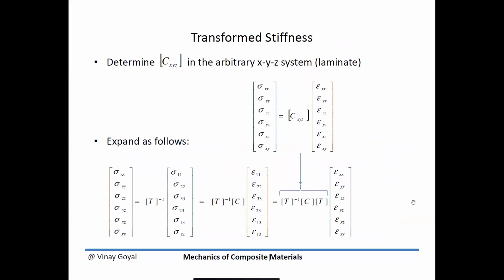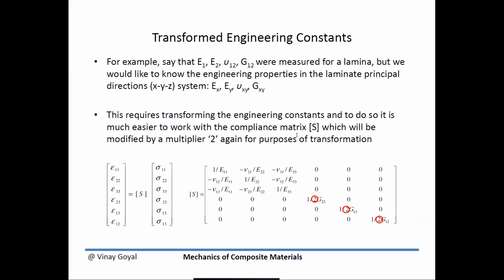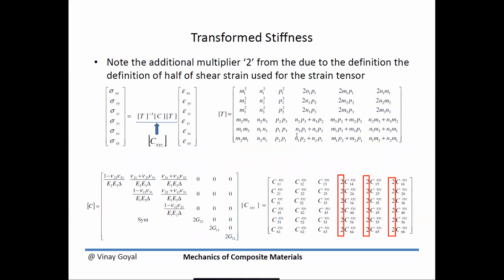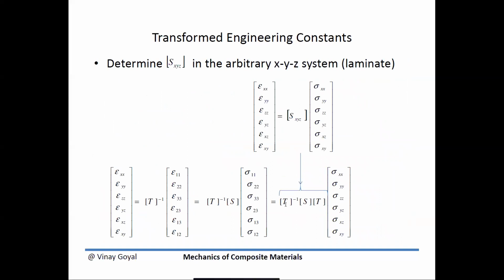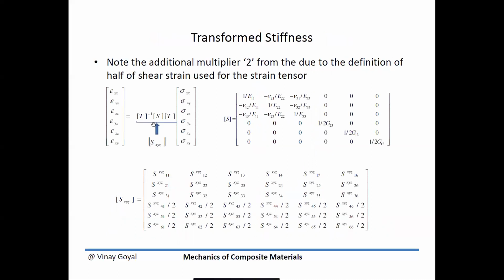And then instead of working with C, the stiffness matrix, we worked with the compliance matrix instead, because this one doesn't need memorization and is easier to work with. So now I have the laminate strain, the laminate stress. I can go through these transformations to find that, given T, the ply angle, I can find T fully, which is a 6 by 6.